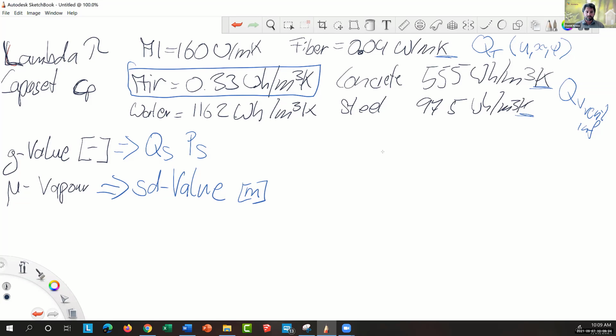And then we learned that the difference between the demand and the load is just that climate part of it. In the demand, we're using the heating degree hours that you just calculated earlier. And in the load, we're looking at the maximum thermal difference. And with this, you understood the magic formula, how that is all coming together at the end.